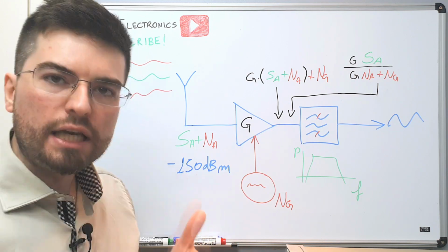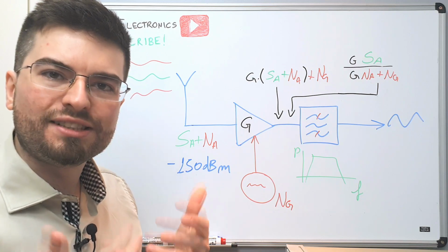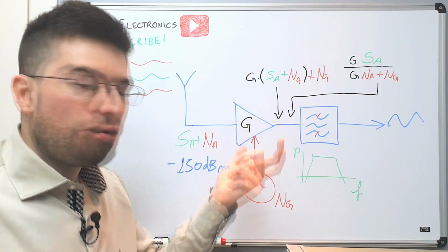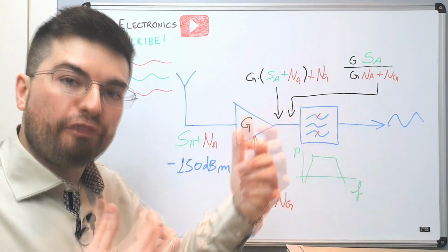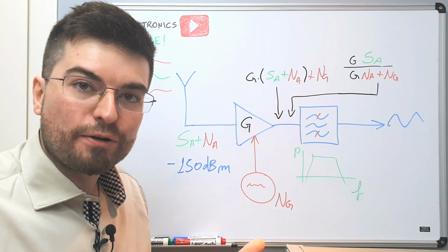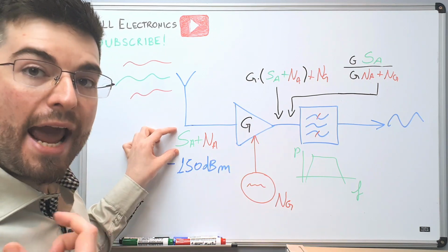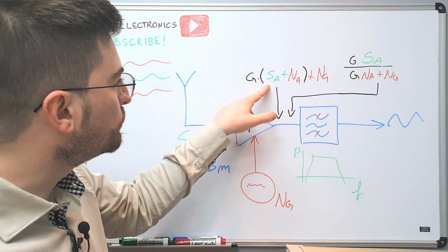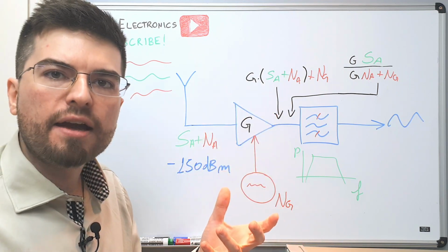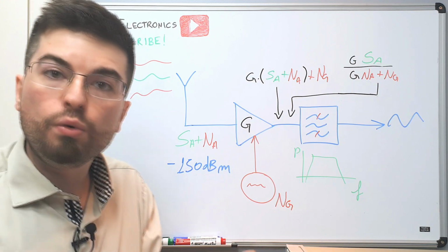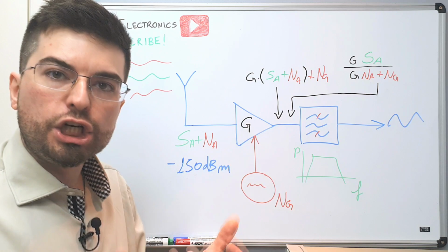We saw it here. If we are only thinking about signal level, we could always add an even larger amplifier or one more amplifier to amplify even more to have a larger signal. But of course, this is not the real world. If we look only at the signal amplitude in the output of the amplifier, we don't have enough information to know if the receiver will work, because we don't know the condition of the noise.